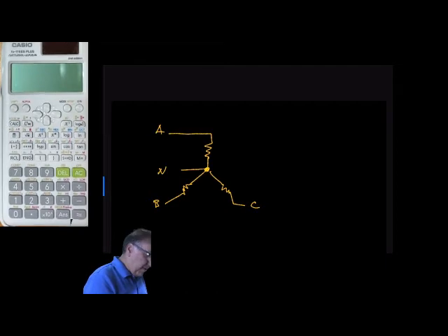So here's how. If we configure 3 resistors in this configuration, and this is called a Y configuration. It's an upside down Y, but you can see the Y here. So we have 3 phases coming into each resistor and a central point and we tie that to neutral. So if we put a voltmeter in here, we would measure 120 volts AC.